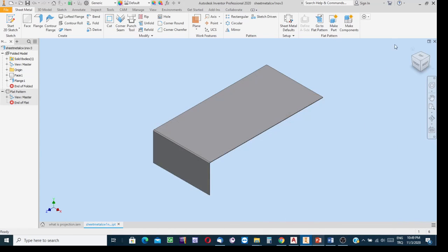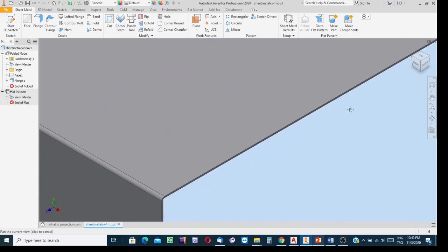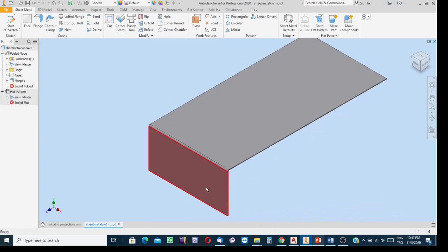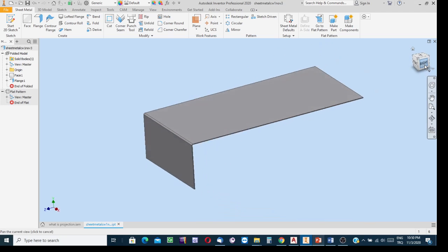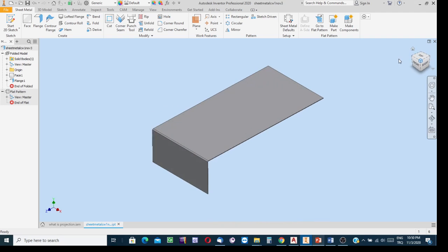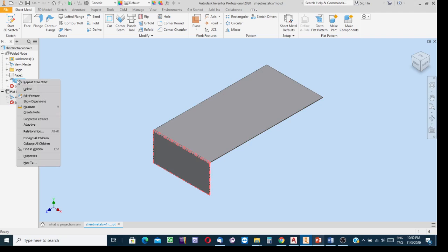Okay. Zoom in, and by the way, here this flange, you see in this orientation, can say that it is the folded part in the down direction. But if the part is to be in the upward direction, then we'll see how. Bring the cursor onto this icon, it corresponds to this part, and say that edit it. Right click the mouse, and then select edit feature.